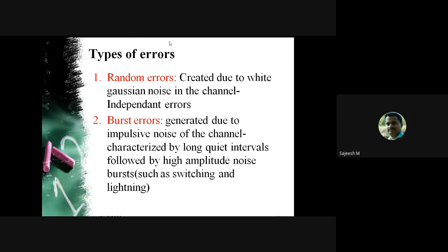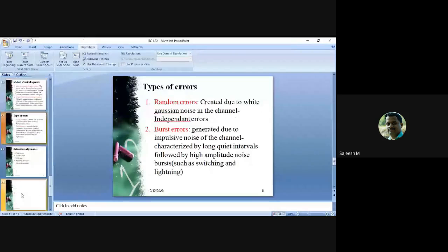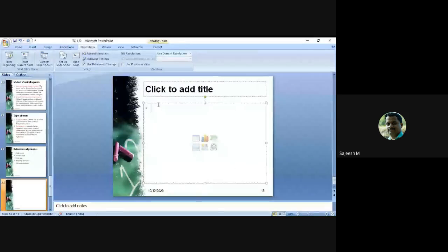I think you are following. That is, 000 is the message, then we are adding an extra bit 0 as the check bit. Then if it is 001, the extra bit is added, giving 0011. That is the code word corresponding to message 001. That fourth bit is the check bit, parity bit, the extra bit we are adding.